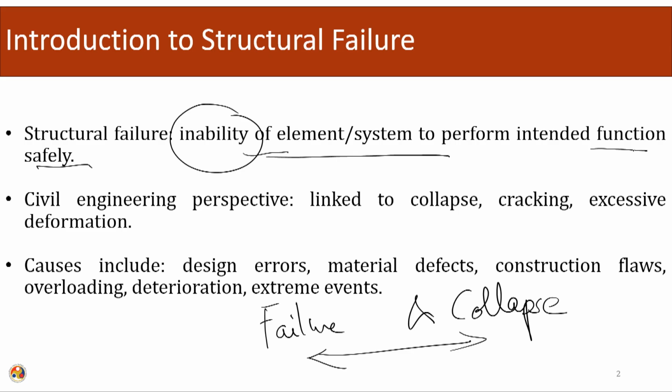Let us say we are designing a column. Let us say we have a stout column, which means that the length is short. If we are applying a load that is acting directly at the center of the section, we are expecting only a compressive behavior. We are making sure that the compression will occur and there will be no buckling in the section.